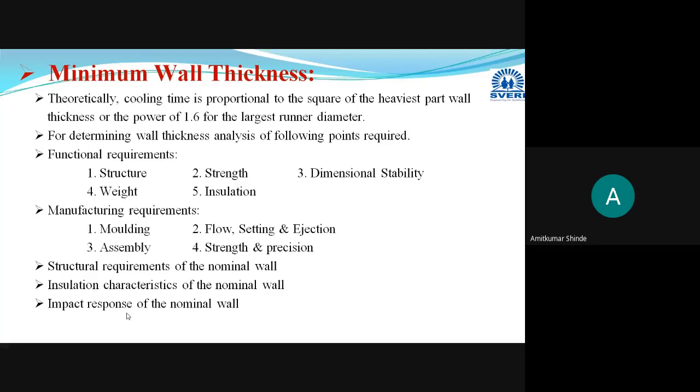Whenever you are using thick sections, it will increase the stiffness of that particular plastic material. So you have to take proper care of these points while selecting the wall thickness or nominal wall thickness.